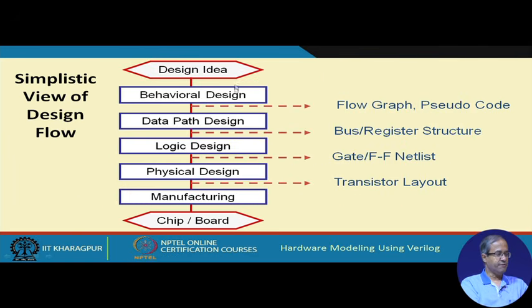Talking about the design flow, the simplistic view is as follows. Starting from a design idea, we have to finally come down to our chip design or a board design. We typically start with a behavioral design, which is in the form of pseudocode in a hardware description language or some kind of flow graph notation.